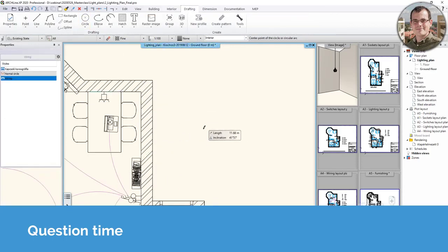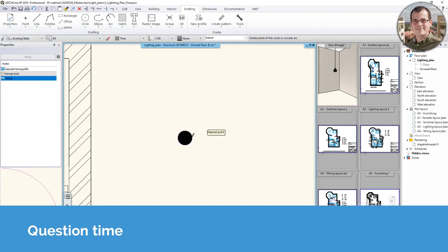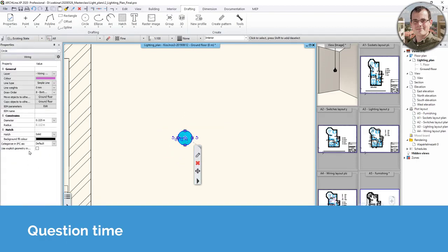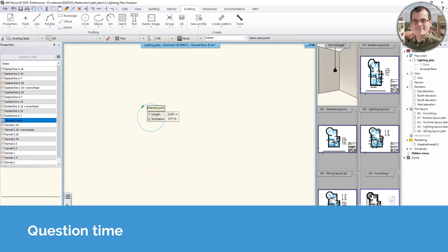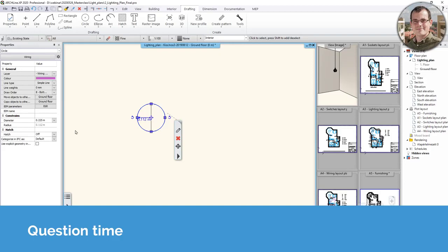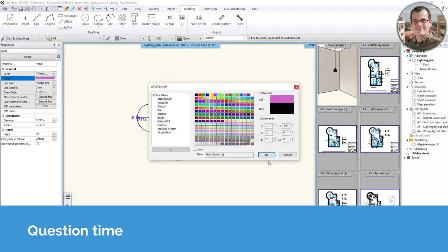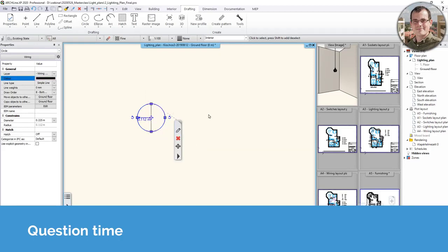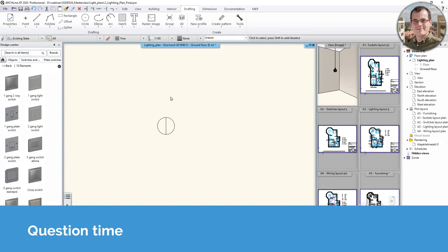So let's say I want to have a square which has, well, I don't need to have a solid hatch pattern. I need to have instead like a vertical dash maybe, and the line weight should be a black one. So I created this very simple stuff, and I want to create this into a light symbol.